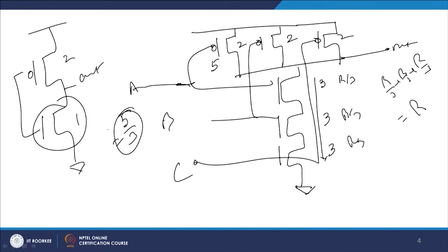So, therefore, you see, the more complicated the gate is, or the larger the number of inputs available to you, the larger will be its logical effort, right, because it becomes more difficult for the whole gate structure to give the same amount of output current as your small sized inverter, right. So, this is how you calculate the logical effort for all the other gates, right.